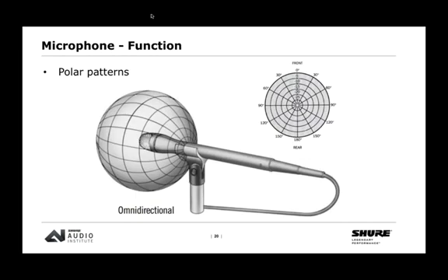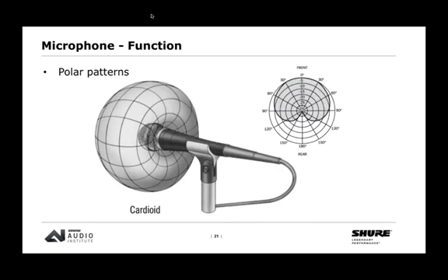So let's look at polar patterns. Many times we've been asked, well, just show us the best omnidirectional mic you can have because we want to pick up everybody all around the table. And so you might consider an omnidirectional microphone. This picks up 360 degrees all around, everything equal. The only challenge is that most of the rooms that we're putting microphones into these days do not support an omnidirectional microphone. If we had a noise criteria rating somewhere down around 15, we could probably get away with it. Wouldn't be too big a deal. But the reality is they're all up around 30, 40, 50, and we need something with more rejection to reject more of that ambient sound.